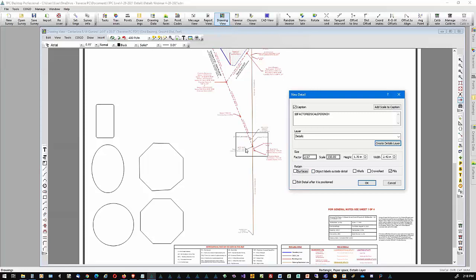Very likely you do. So if it's a survey object, it could be a lot label, a line label, point label, anything like that. If it's outside the area of the detail, but the object that it is labeling intersects with it, the object doesn't have to be entirely in, like this line is a little more out than in, that doesn't matter. The line is going to be shown in the detail. Do we want the label? That's what we're talking about here with the object labels outside detail. I'll go ahead and turn that on.